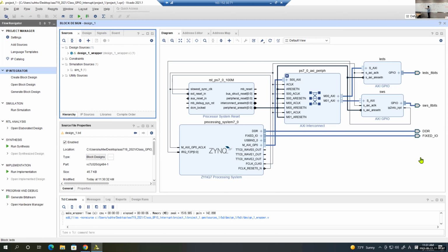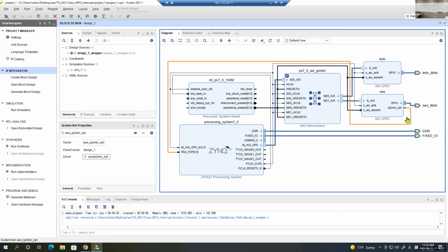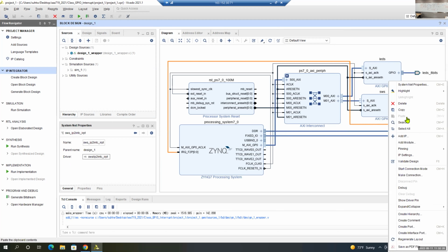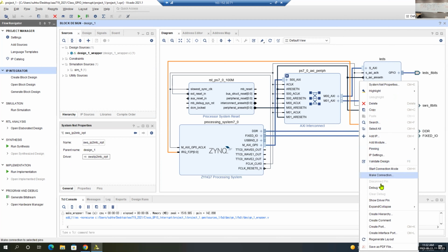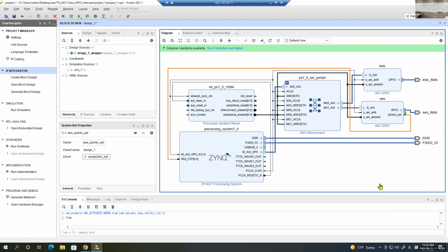Then the question is, can you monitor that internal line that is inside the FPGA? So Xilinx is providing that capability, an internal logic analyzer, not the external logic analyzer you have. You can deploy an internal logic analyzer. It's a very simple process. You click on this wire that I want to monitor, right click on it, and look at this, debug. Okay, debug.